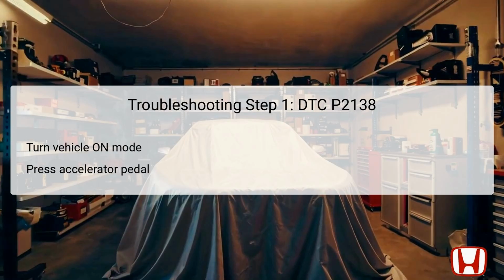It's essential to ensure that this initial test is performed without any obstructions or issues that might interfere with the accelerator pedal's operation. Observations from this step will give insight into how the PCM responds to the APP sensors under load and may indicate whether the problem lies with the sensors or the wiring.